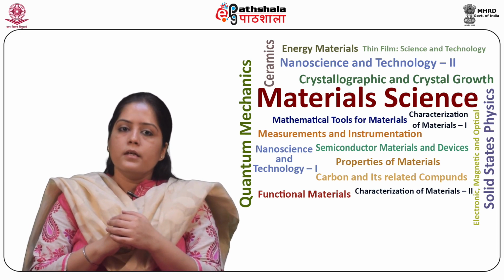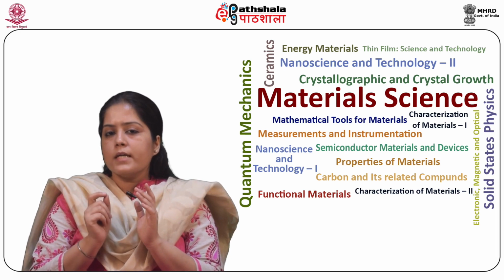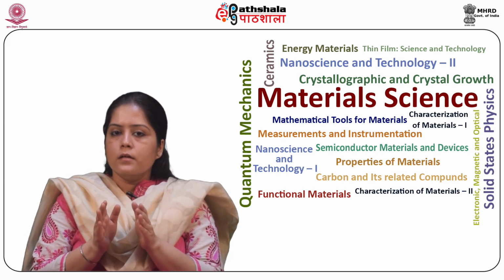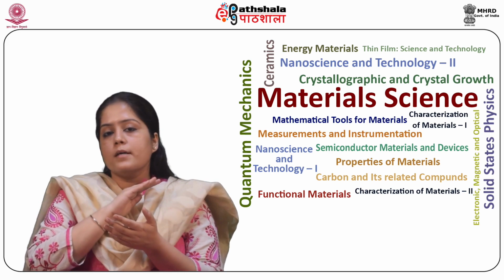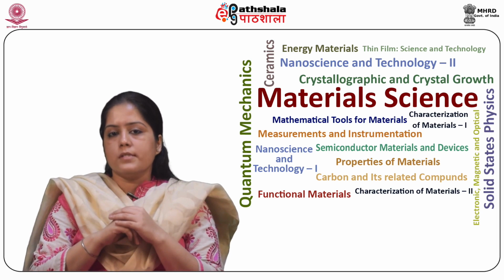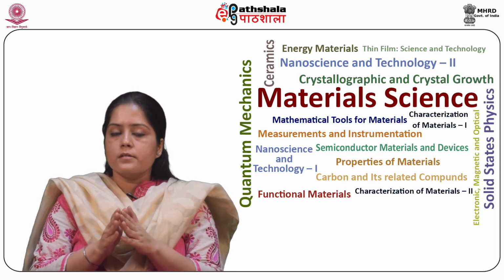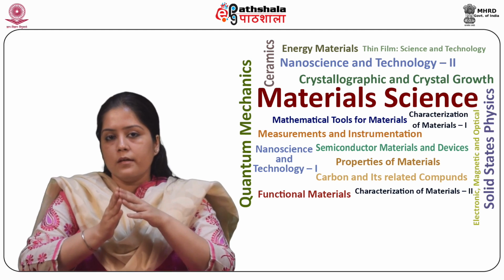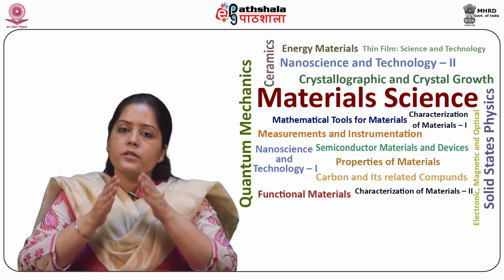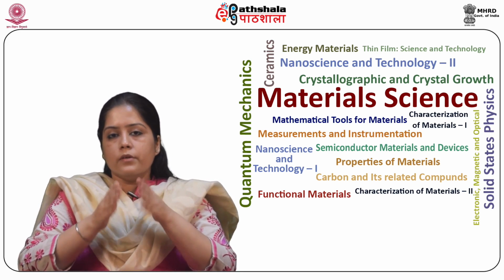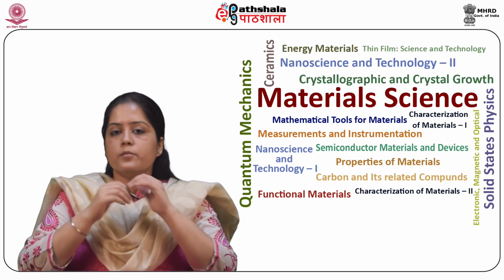And third, if the fabricated cell is quite thin, then some of the light having suitable energy will pass straight back out of the cell. This determines the minimum thickness of the semiconductor material required. Hence, direct band gap material will require less material than indirect band gap material.